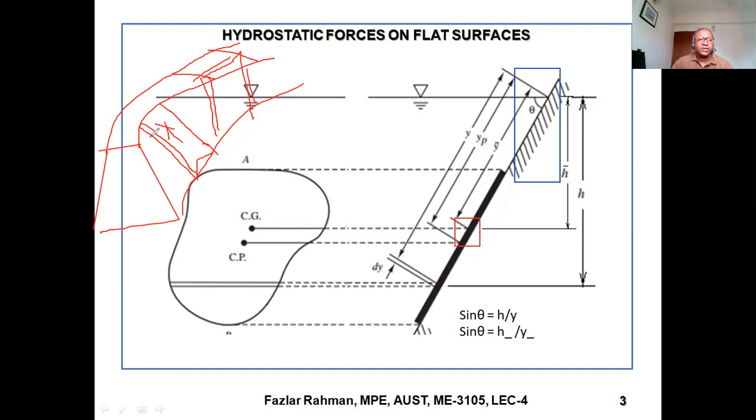So you see this plate is not completely horizontal, it makes a certain angle. If I make a line like that, that means it is making a certain angle with the horizontal line, right? So this one is showing over here. In that case, our plate is only this mass. This mass is the plate. So if you have some mechanism, you can slide the plate upward, then the gate will be open. If it is pushed down, the gate will be closed. But when the water level is this much, then you need to figure out how much force is on the plate. Where is the resultant force working? Then you start to design what the thickness and the material will be.